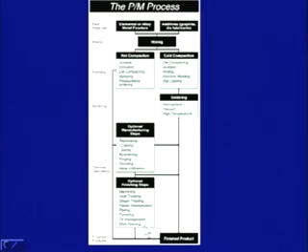Now, again going through the summary of the powder metallurgy process. This process makes the powder of the metal, then this powder is mixed with die lubricants or with different types of additives. The mixture is then pressed under the compaction processes. The compaction processes can either be cold compaction or hot compaction. Then it is sintered. Sintered means it is heated at an elevated temperature. After that it can be used as a finished product, or it is subjected to some optional manufacturing steps.